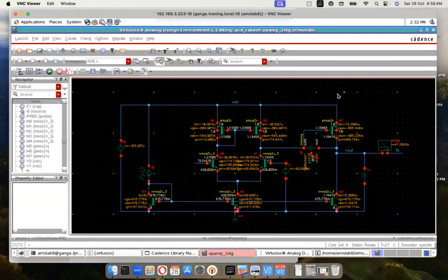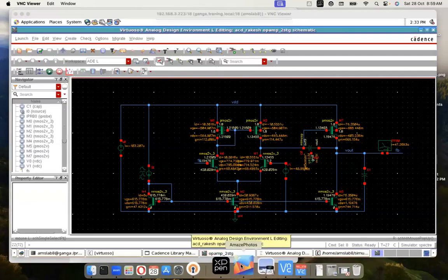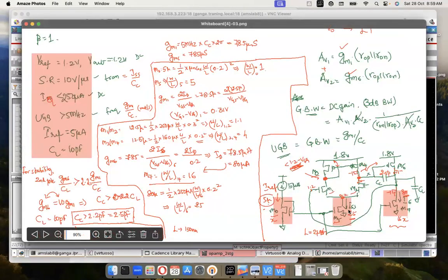Now let's come back and see some of the operating points that we had earlier decided. You remember it was a 5 microamp current. Okay, the 5 microamp current is coming here. The M2 or the input stage current was what? You remember that? The current here, ISS, was? Where is the value of ISS? 25 micro. Because the input transistor is 12.5, the overall current is 25. But let's see whether we got that.